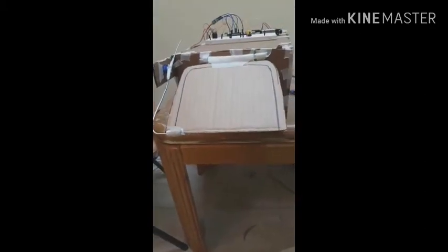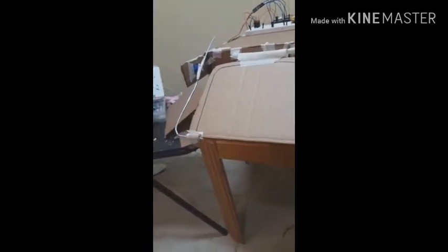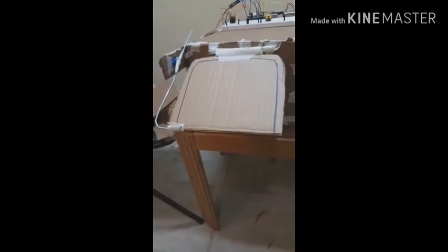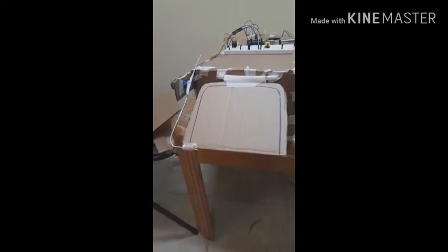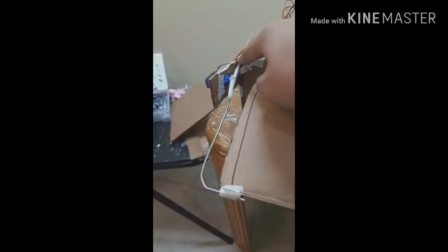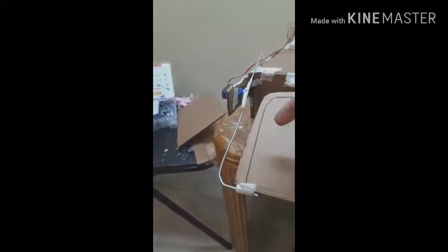So the code itself is functioning, and the way I want it to work is functioning. All I have to do is make the code opposite, so when it comes in front of the sensor, the hatch actually opens. And the way I would do this is by just changing the degrees, so switching them around. I would also cut this extra piece of wire so I could increase the degree a bit, so the hatch goes further up.